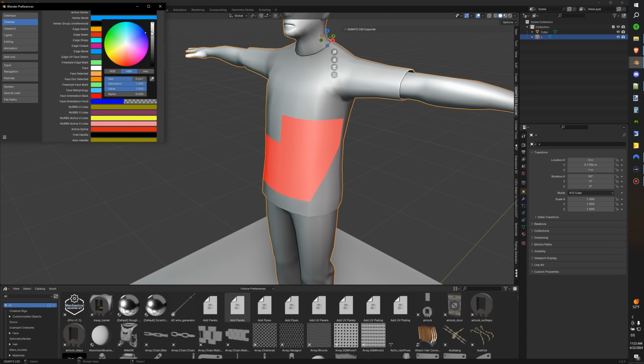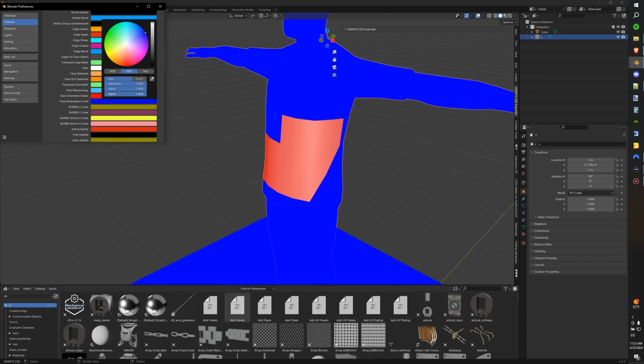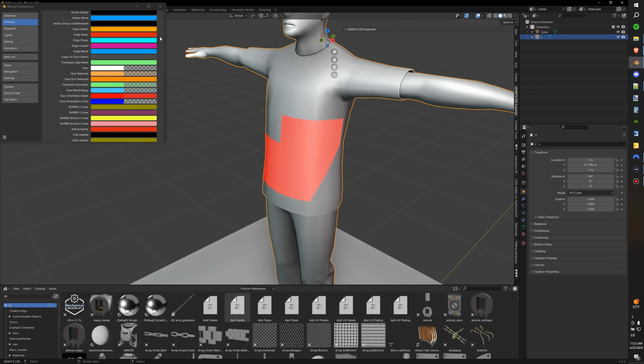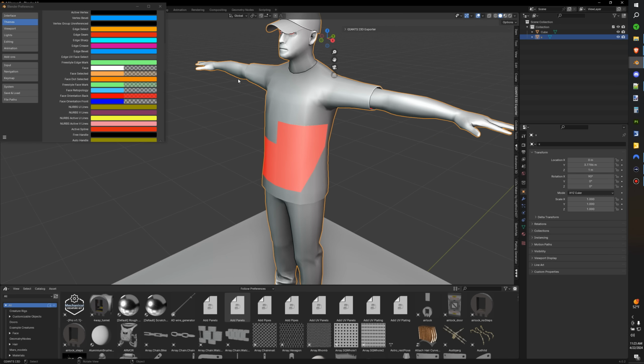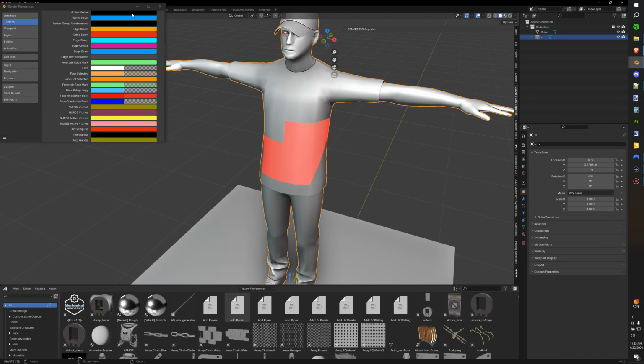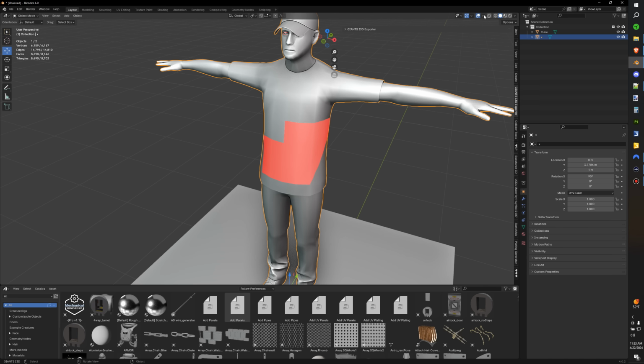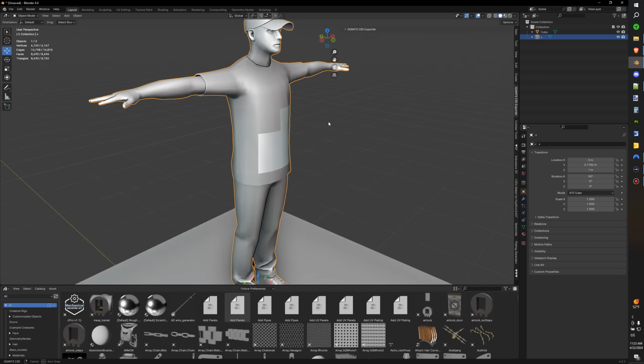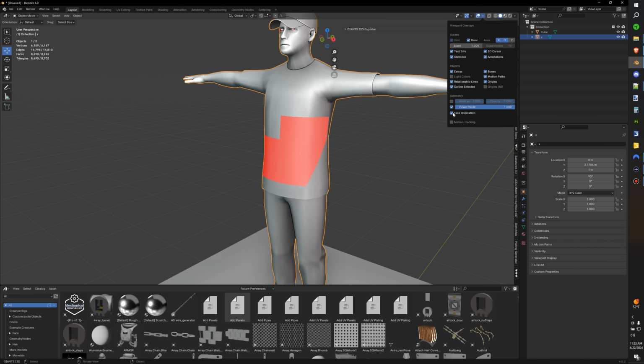You want to click right here and change this alpha. It'll be a 1 when you're looking at it. You want to change it to a 0. And if we don't change it to a 0, everything will be blue like that. But we're going to change it there. So only the faces that are facing the wrong direction show up. This is so useful while you're modeling because you don't have to stop and go back. The actual setting to view if the faces are facing the right way is under this little tab right here where it says face orientation. And if we uncheck that, we can see that there's drastically still some difference there in our modeling, but I like to leave that on.